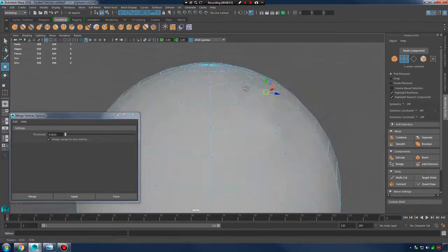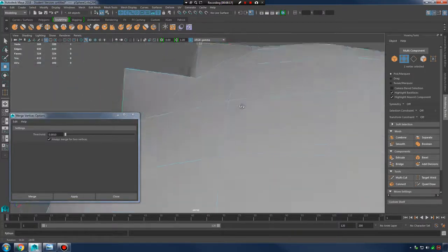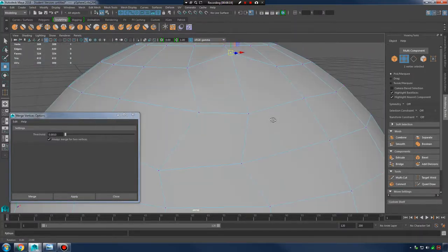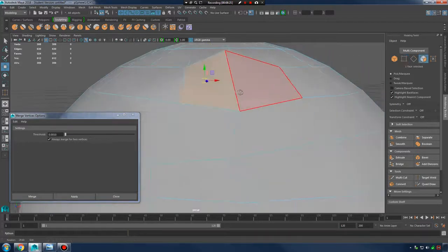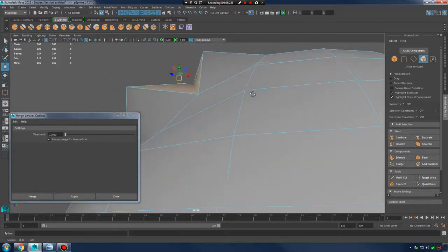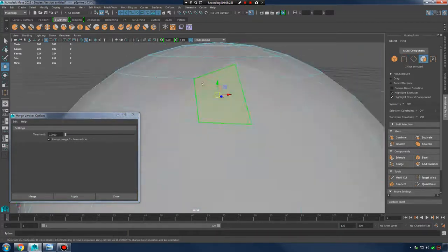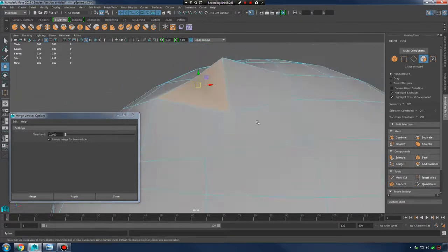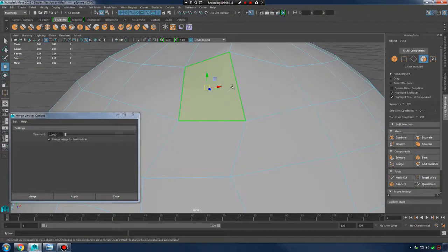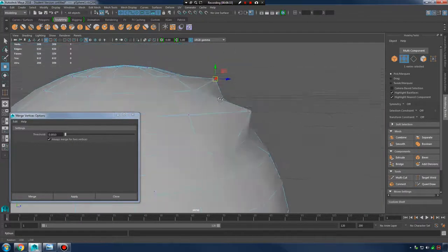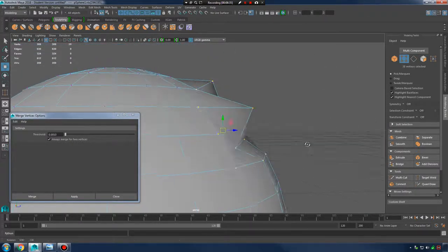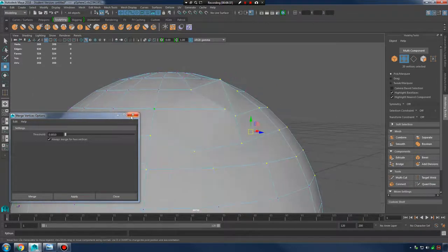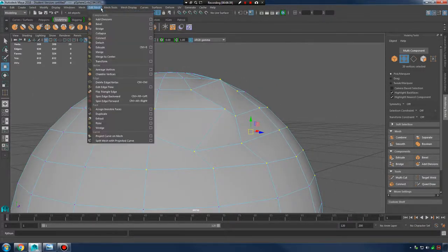It's very tricky to do it without creating non-planar faces. So we have this face right here that's just all messed up. We have like a valley here, but no geometry to define that valley. So it's non-planar. With these messed up vertices, I just want to get some unique geometry so I can show you guys what average vertices does.